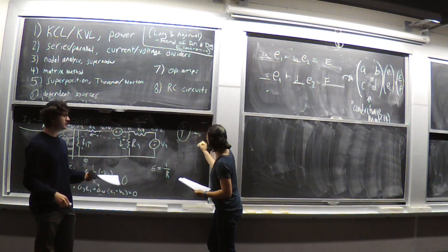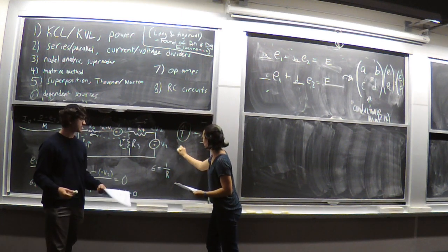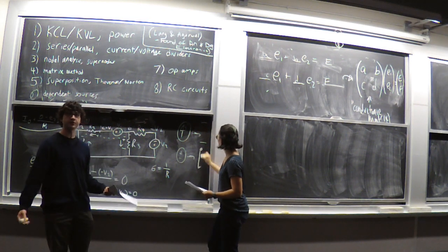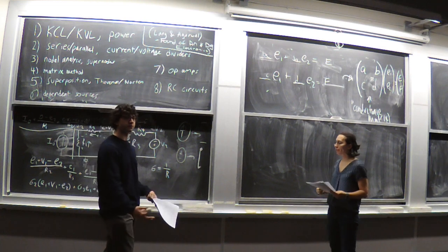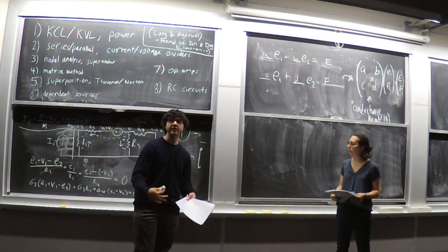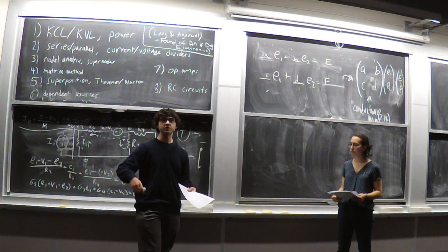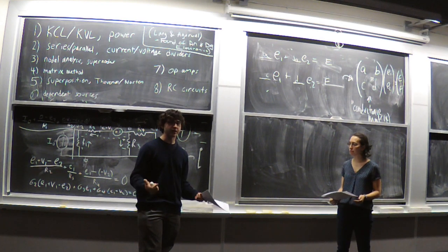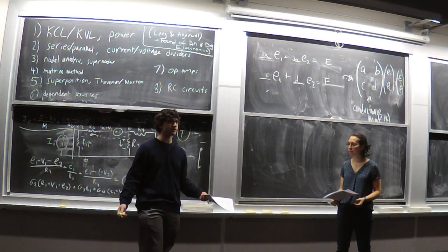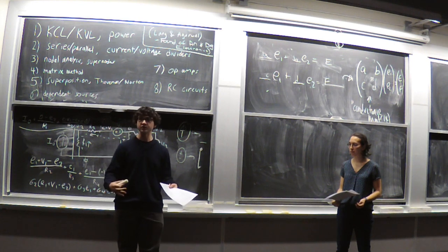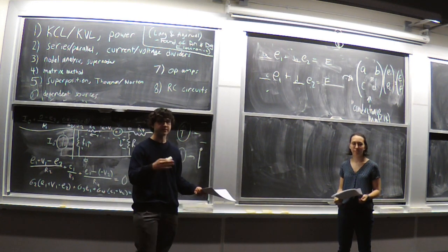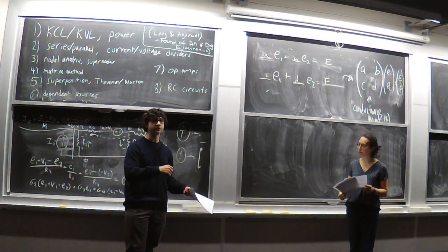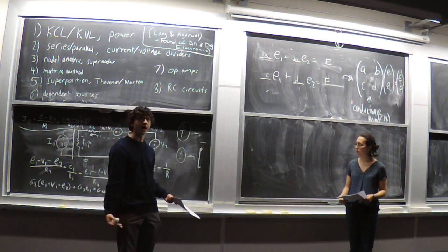Yep. And the intuition behind that makes a lot of sense. When we say that we turn off a source, it really means that we set its value to 0. So for a voltage source, we would be setting it to 0 volts. For a current source, we'd be setting it to 0 amps. And if you think about it, what does it mean for a voltage source to enforce that 0 volts will drop across it? What circuit device that we use all the time in every circuit we've ever built has 0 voltage dropping across it? That's a wire. That's how we define a single node. It's where we just have all wires connected. There's no voltage dropping anywhere. And so that's why a voltage source being turned off, set to 0, turns into a wire.